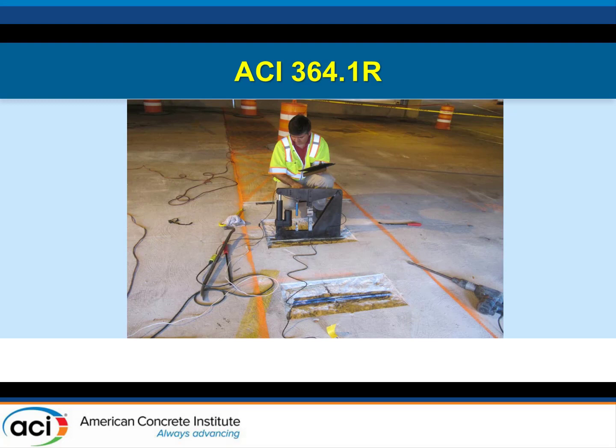I think the only downside to it is that you are cutting the tendons open. In the case of a parking structure like this, we're cutting them open in the most vulnerable zone. So it's not like we're enthusiastic about doing this. You can run these same tests on the underside, inside the building. We couldn't in our case, but it's probably the most reliable way to get some really good data on what's going on with the tendons.